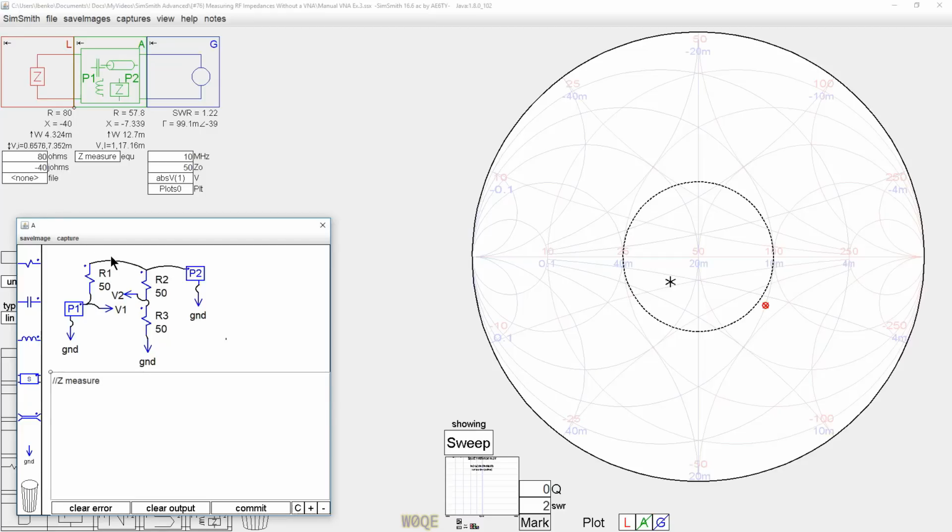So what we're going to do is make a voltage divider here. We know that this voltage here, from circuit theory, is this voltage up here times this impedance divided by the sum of these two impedances. And of course you have to keep account of phase and everything. But SimSmith can do this for us very easily. There's a reason for using this voltage tapped down, and that's because I can use two channels of the scope on the same range.